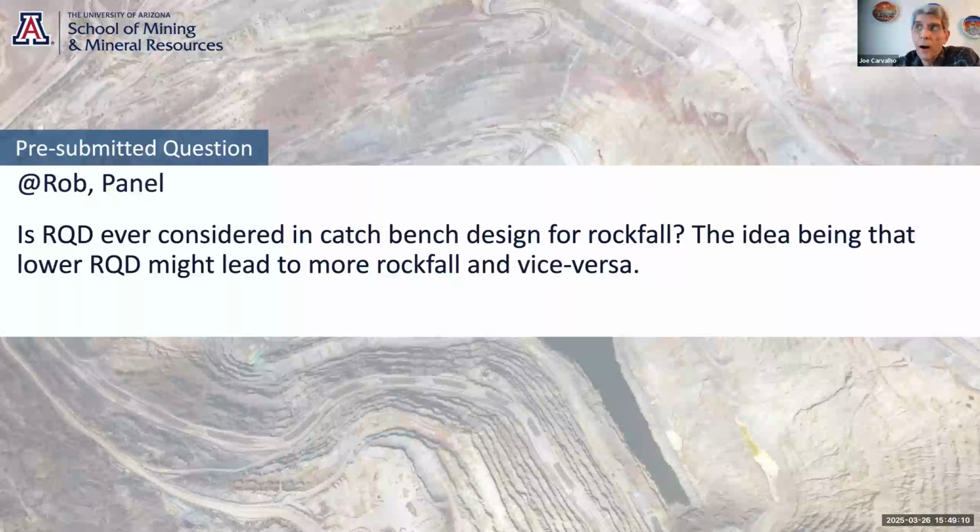So I've seen in South America open pit mines where RQD is very poor, below 10%, where you basically fill in all the benches and you end up with a continuous slope of scree. So it may be possible to put a differentiator of what kind of catch bench mode you have to be on, whether it's just a continuous bunch of scree or trying to catch big rockfall.